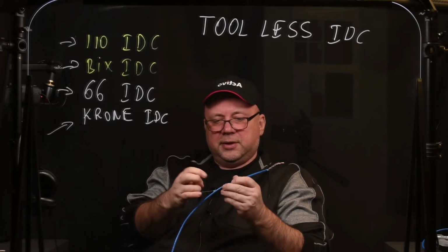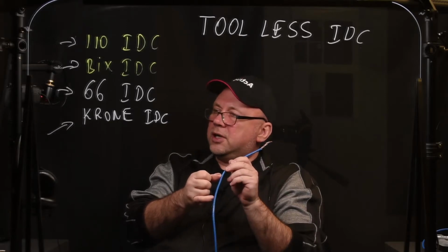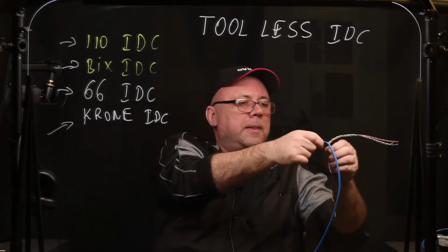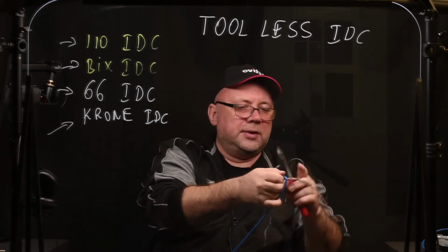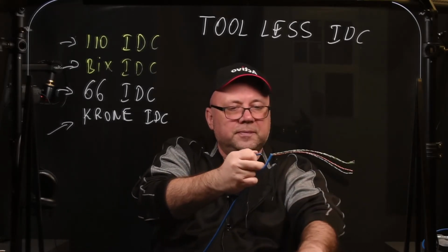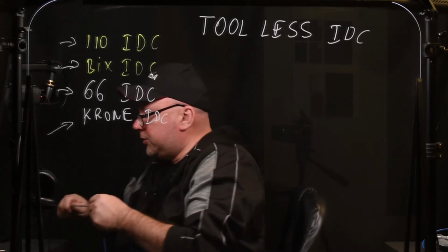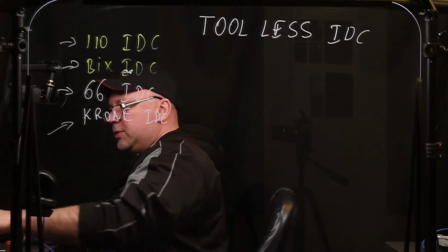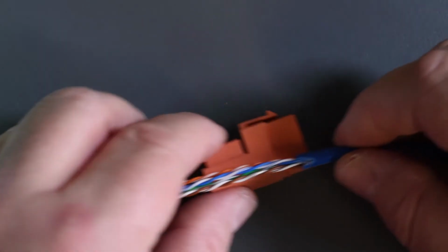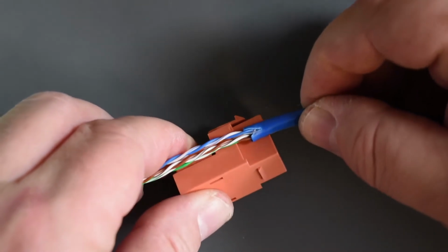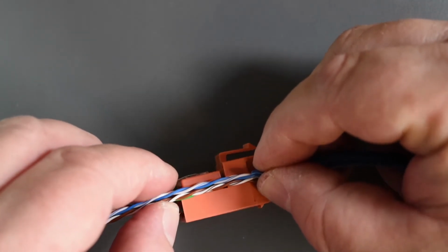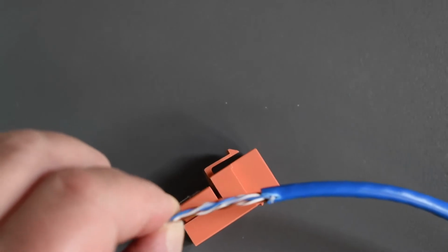All right. So let's just pretend that, okay, here it is. I just made that right to that mark. And then I'm going to peel the cable, grab it, and cut the insulation off. Cut the fluff. Always cut the fluff. Okay. And then remember the length that we established. I'm just going to measure that length here. It works really good with me here. So you put that cable right up to here, and then just grab that. And this is as much as we want to cut off.